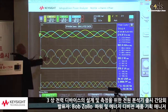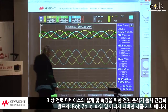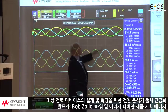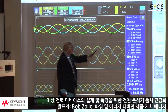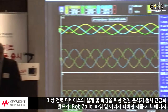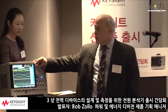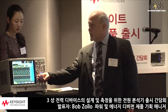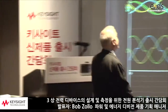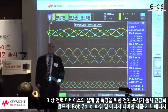Okay. So let me explain what you're looking at. This portion here is a live updating information of the waveforms, and this portion here is the power quality measurements. Now, if you look, you can see the dots are changing. This is updating data, but like with any oscilloscope, I could grab the time base knob and make changes in real time as far as the time base is concerned, or if I want to change the amplitude on one of the signals, I can do this as well. So from this standpoint, this portion of the screen behaves exactly the same way as an oscilloscope.